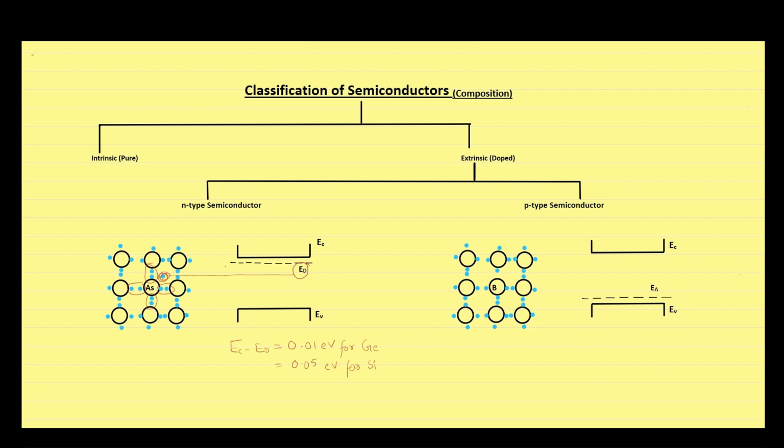When semiconductors are doped with donor impurities, the hole concentration also decreases relative to the intrinsic semiconductor, as the higher number of electrons increases the rate of recombination of electrons with holes. Therefore, in an n-type semiconductor, the concentration of electrons is much greater than the concentration of holes. n in n-type represents the concentration of electrons, whereas p represents the concentration of holes.